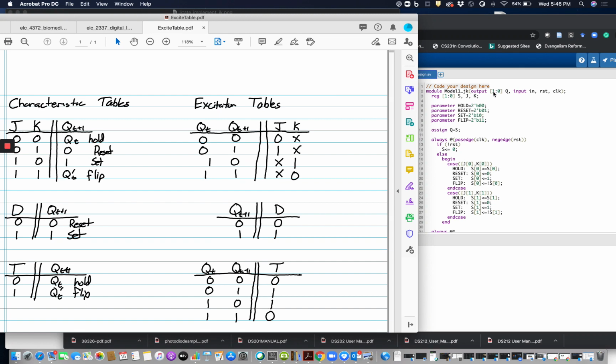Now, you might be wondering, why not just make an output reg instead of having a state internal? That will work for some systems. Technically speaking, in the Verilog standard, anything that is an output, you are not supposed to be able to read. So if you've got an output, you can't read it, and that's not good. So that's how that one goes out, and that's why I do this, because this will work with every single system that's out there. All right, let me.